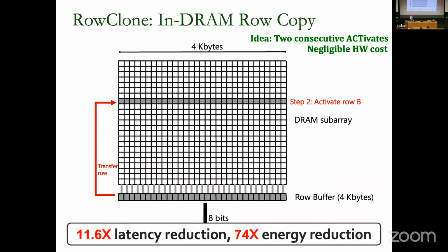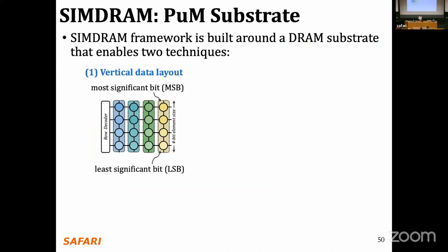Implementing some network to connect all of those different DRAM columns inside the DRAM subarray is quite costly because, again, recall that here we have 4K columns for DDR3, 8K for DDR4, so 65,000 of those columns. So this network would be quite costly to implement. Instead of implementing such a network to enable us to propagate carry while doing arithmetic operations, we are going to transpose the data on the fly.